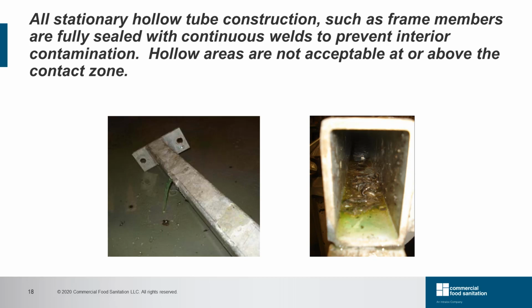If used, make sure it is fully sealed with continuous welds to prevent interior contamination. In wet environments, hollow structures may contain water and soils, introducing microbial issues. Potential pest issues can occur in a strictly dry environment. The photos display a situation that can be associated with unsealed hollow profiles.